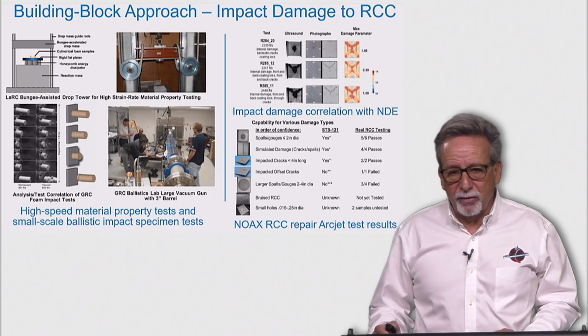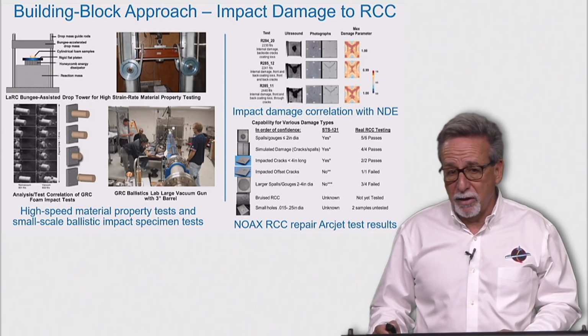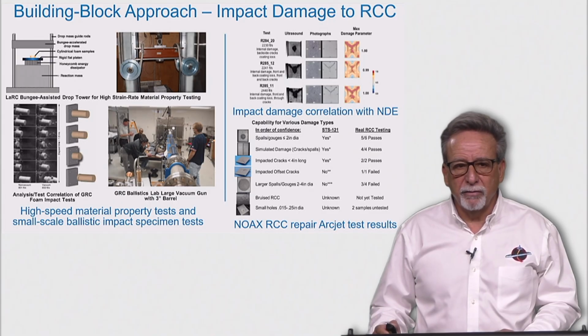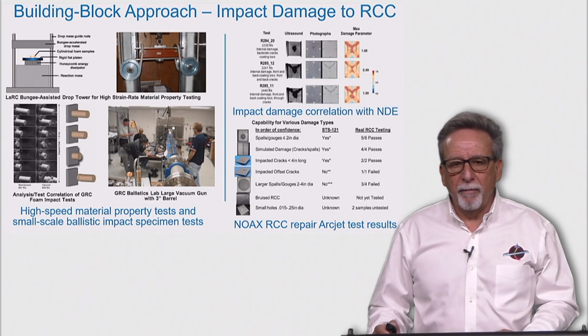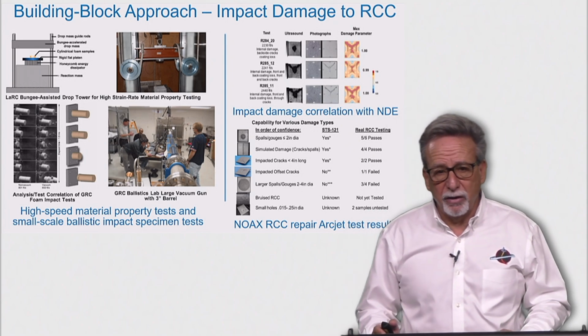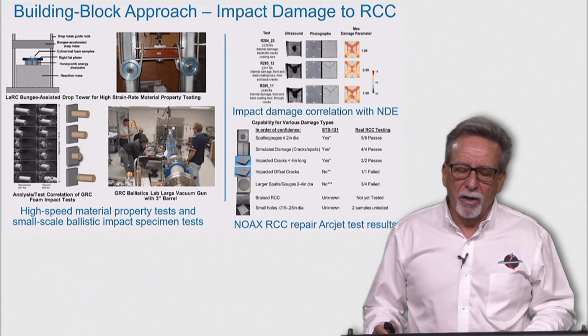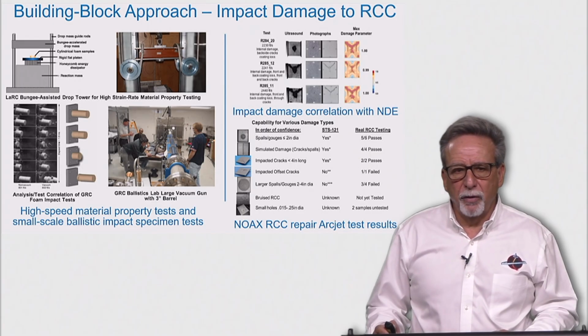How we then take the damaged specimens from the impact test and conduct non-destructive evaluations of each specimen using a variety of techniques shown on the right: ultrasound, thermography, x-rays, etc. And when we compare the NDE results with our numerically predicted results of damage, we can finally take these impact damage specimens and evaluate methods to repair the damage, then subject the specimens to simulated reentry heating conditions in small arc jet facilities to predict whether or not the repaired specimens would have survived Earth entry. This is what we call failing smart, fast, small, cheap, early, and often.